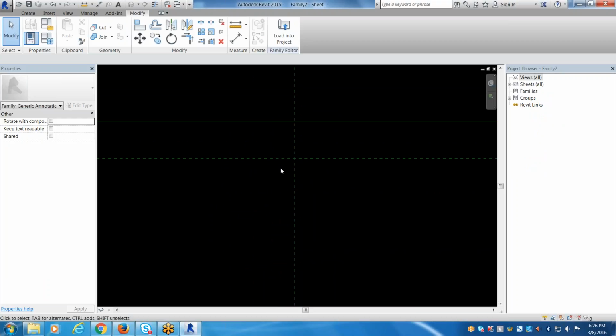So you both know, Revit, unlike AutoCAD, can't go infinitely small. In AutoCAD you could zoom in, draw tiny, zoom in more, draw even tinier. This has a limit of 1/32 of an inch, meaning we can't draw any smaller than that. No symbol is ever going to be smaller than 1/32 of an inch.